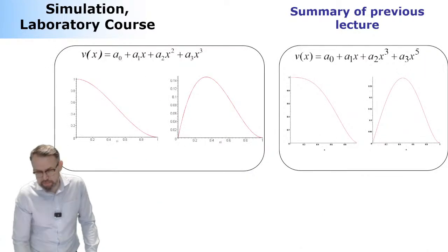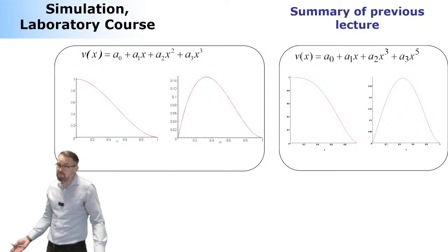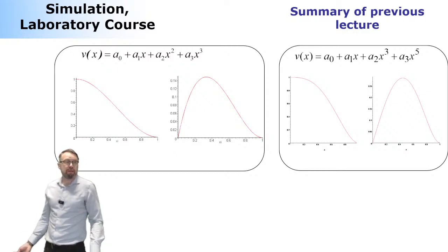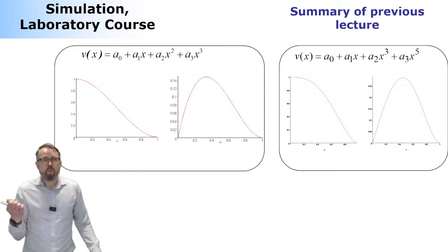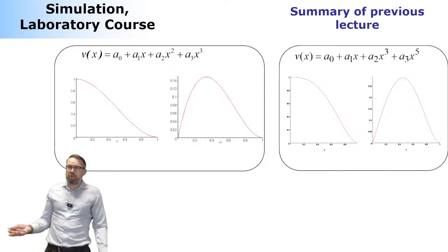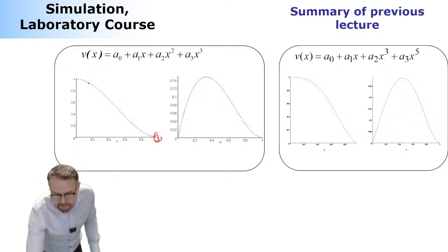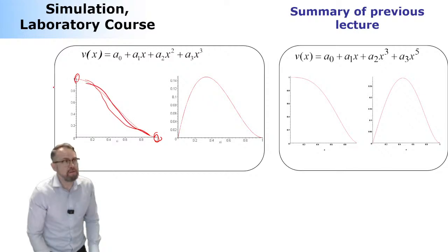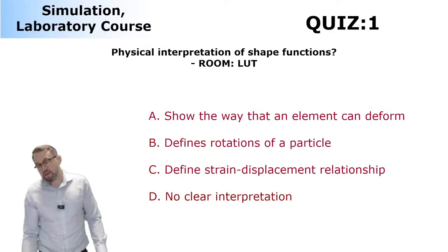Okay, so that's a polynomial. So this, again, is a comparison of different shape functions. They're just different shape functions. But this is the soul of the finite element method. That's what the finite element method is about. Remember, I said that we have these nodal locations. But more important than the nodal location is to know where each of the particles is traveling. This is information we must have to be able to create the stiffness matrix and other components.